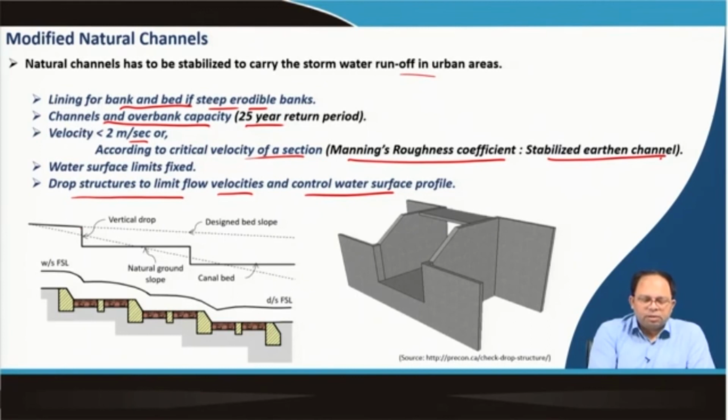So, this is the vertical drop that we are doing, and you can see in the structure how we are doing that. We are modifying the channel so that some amount of impounding of water happens at certain levels. So, water falls down, because otherwise the velocity generated would be too high. If it was a uniform slope, the velocity would gradually become higher, but if it falls like that, the velocity is controlled and erosion does not happen. So, that is why it falls from one level to another and gradually moves on.